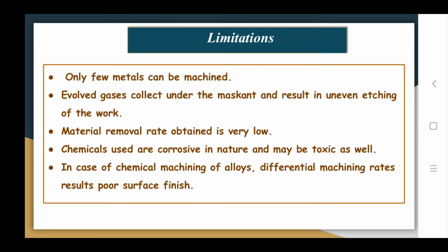Another point one has to keep in mind is that whatever gases are evolved should be exhausted from the area where the chemical machining process is taking place, because they will attack the equipment surrounding the chemical machining setup.